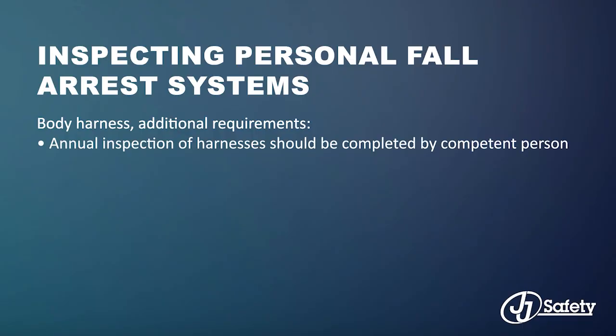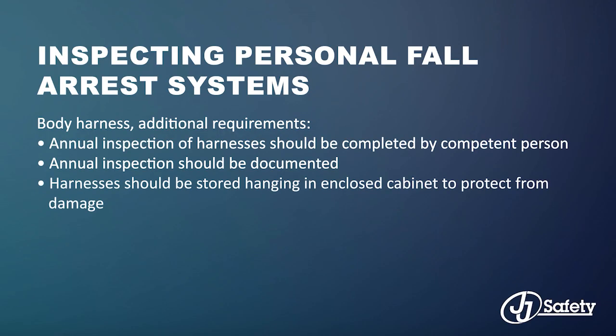Additionally, an annual inspection of the harness should be completed by a competent person and should be documented. Harnesses should be stored hanging in an enclosed cabinet to protect from damage. Harnesses involved in a fall should be removed from service.